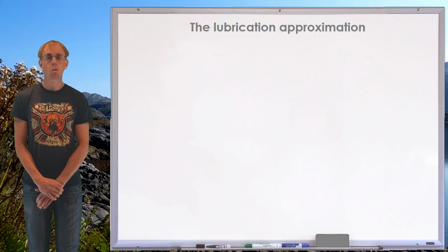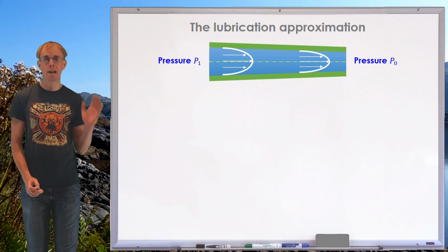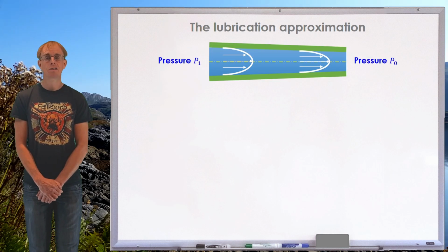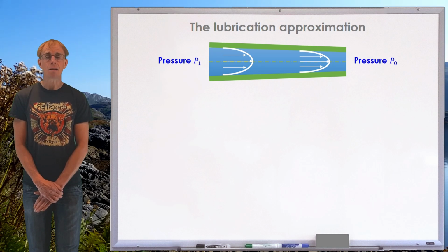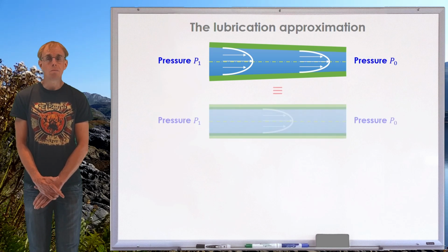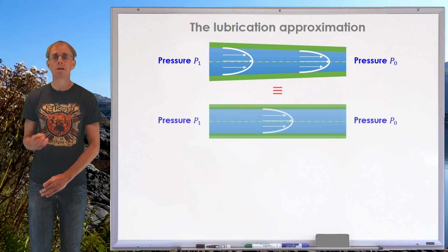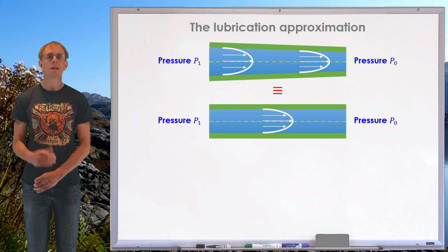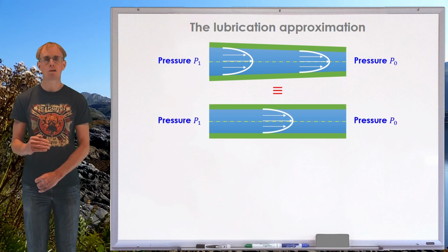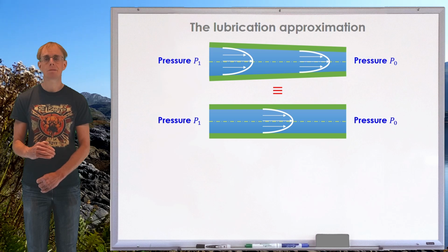It's valid for mildly tapering tubes, and there I've put on the whiteboard a diagram of a mildly tapering tube. And the first step is to assume that really the dominant change in flow velocity is across the thickness of this tube, or the diameter of this tube.